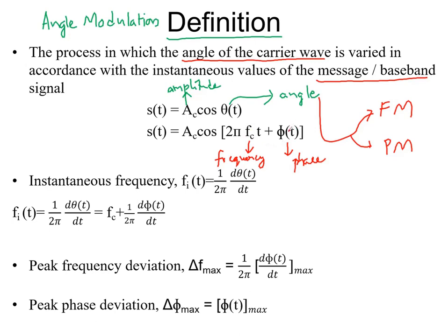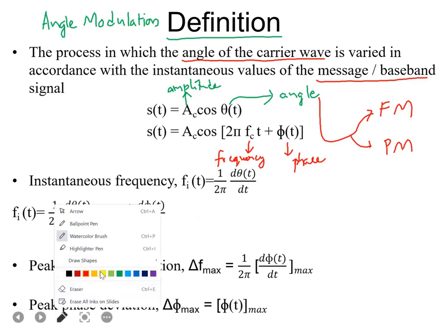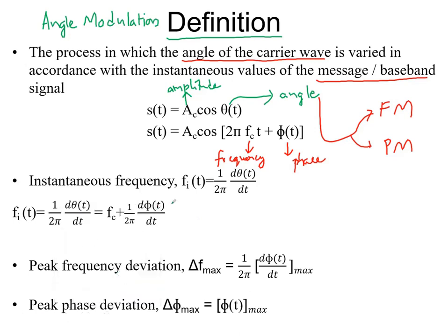Now, going into our next topic. Before studying anything, how will you define the instantaneous frequency of any waveform? The instantaneous frequency is defined as the rate of change of phase for every 2π radian interval of time. What I mean here is, suppose you have a certain signal like this, maybe your s(t).